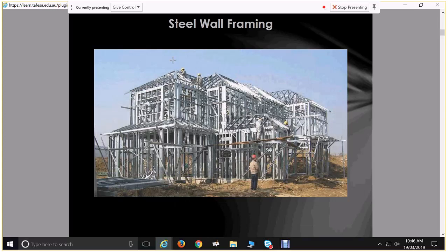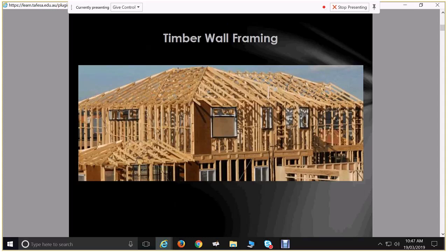Another major difference between timber frame and this steel framing is we were talking about trusses. Once we go with trusses, that's in the engineers' or the truss manufacturers' hands. They do the design, and any modification that has to happen goes back to them. When we've got our timber frame design, if we've got a thorough understanding of AS 1684, we can design that in accordance. So we can use all the rules set out in that to design this.